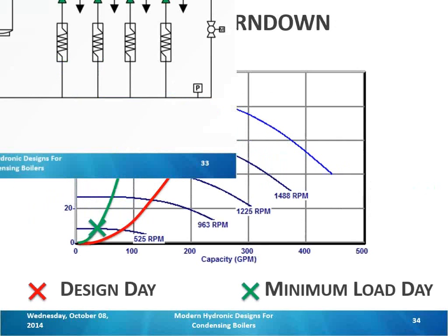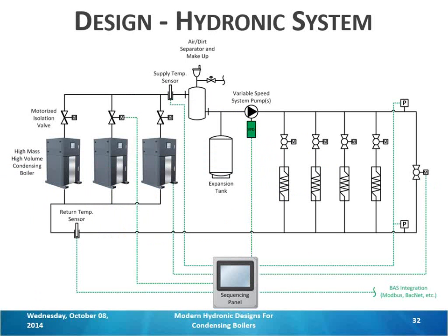If you have the integrated panels, which many boilers do, it's very industry standard. The integrated panels will control each of the boilers and usually the valves of the pumps. But in terms of system control, like VFD pumps, the integrated controls usually will not have that capability. Typically, you'll need a standalone panel or a pump control panel with VMS to be able to do that.